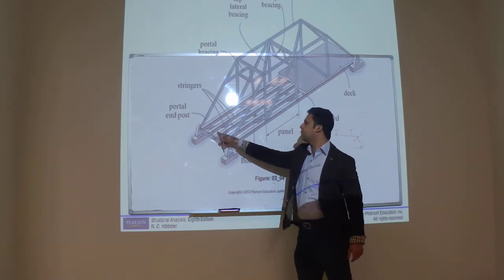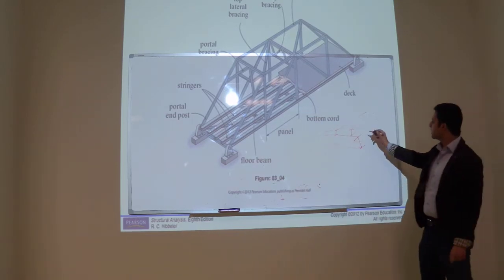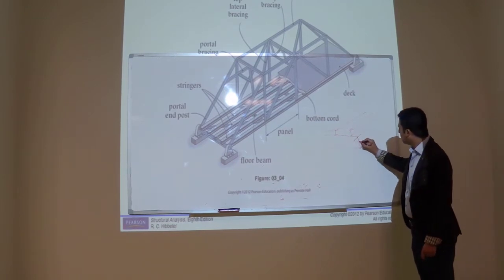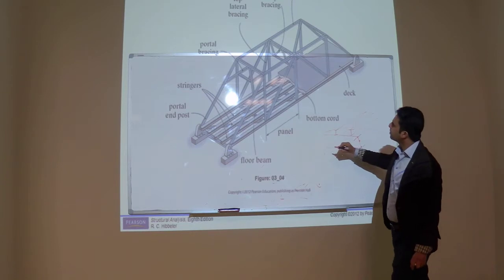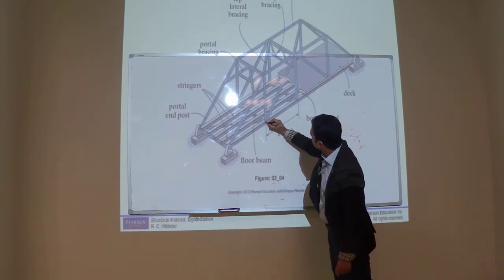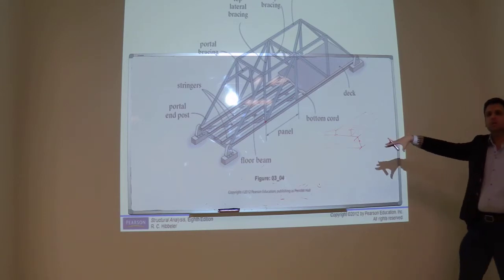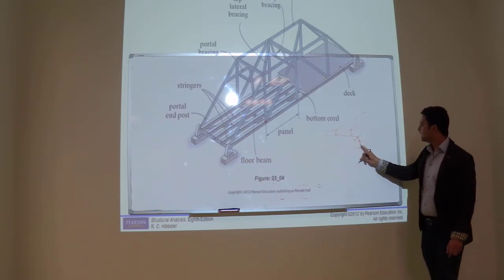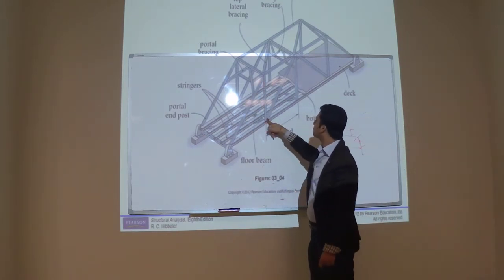These five beams are the stringer beams. These stringer beams are resting on the floor beam, the bigger beam. And this floor beam is connected at this point. So all the load of the bridge is going to the floor beam, and from this floor beam, at these 2 points, we have connected the floor beam with a truss.